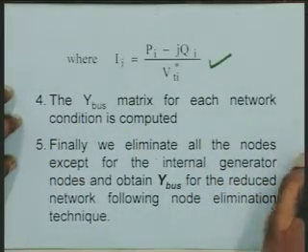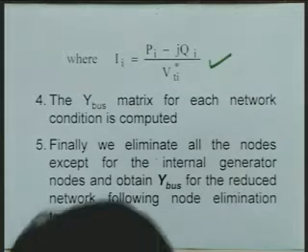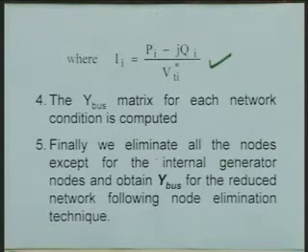Now, once you have done these preliminary calculations, we obtain, using this information, the swing equations. You know that we require swing equations under 3 different conditions: one is the pre-fault operating condition, second is during fault, and third is post-fault. When you solve these swing equations, suppose I start solving at time t equal to 0.